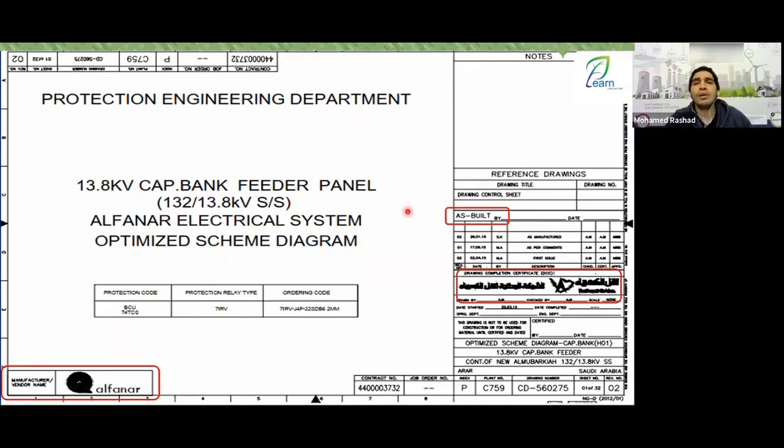You need to know which drawing you are working with, because if the station wasn't completed and you bring me a pre-commissioning drawing, or for example, a commissioning drawing, there might have been modifications made afterward. You need to provide me with the as-built, because you might see something and start looking for the existing axes in front of you, but you don't find them in the drawing, or you might find in a drawing that the axes aren't present in front of you on the panel.